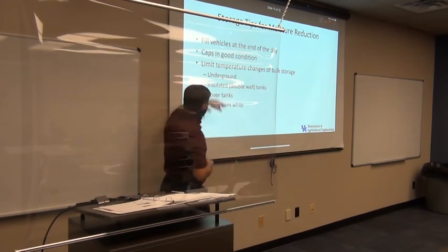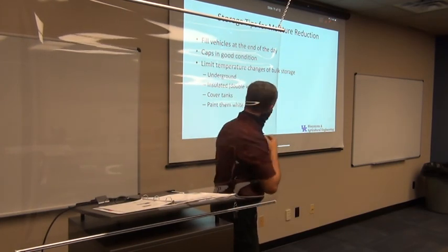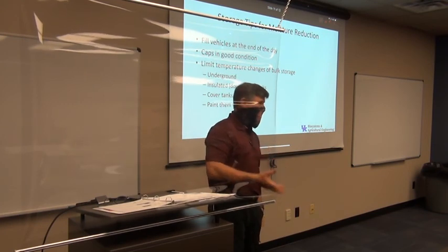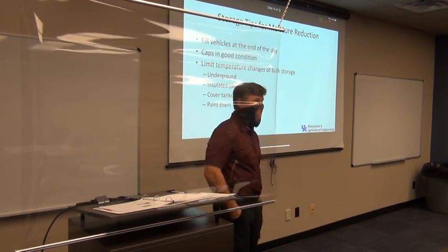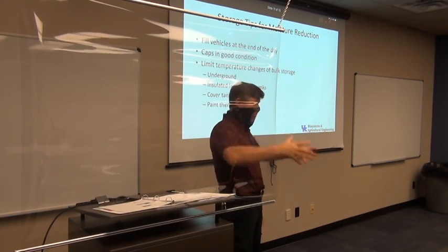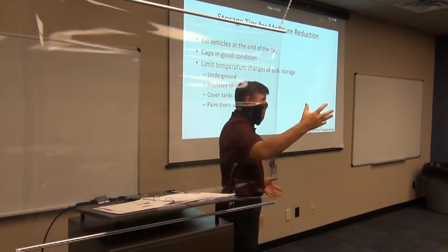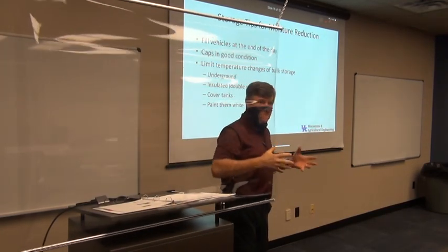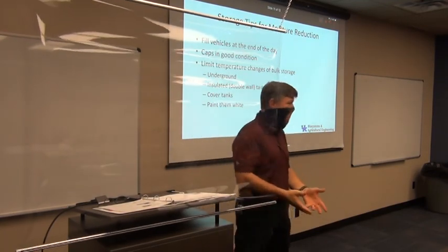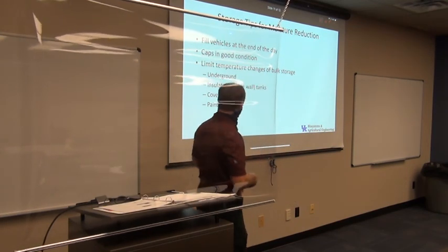All right, so keep your caps in good condition. Here's some more psychrometrics to think about. This is kind of good analysis. If you can, put your bulk tanks, if you've got bulk storage, underground. Why? The temperature doesn't change. Yeah, so I said heating and cooling, heating and cooling. It's pulling the air in, pushing it out, pulling it in, pushing it out. That's what's bringing moisture into the tank. So if I can keep it from heating and cooling, I'm not going to do that. Underground is the best. Getting permits to put things underground is really difficult and really expensive, so most people don't do that, so they put them above ground.